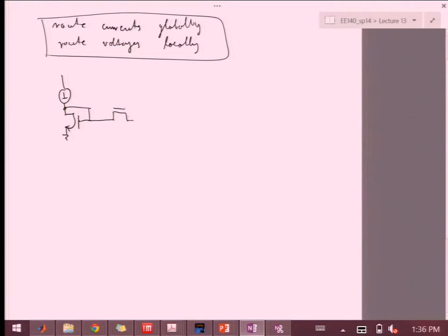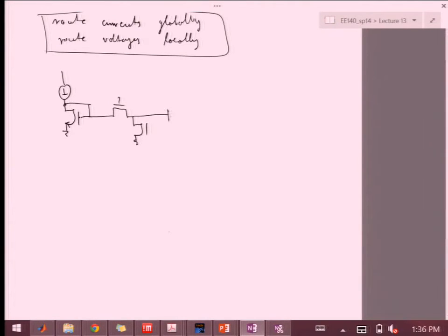So one scenario, one thing you can do is do it like this. Now, this can go on, right, to a whole string of these devices, and then you'll have a power down signal here and its inverse over here. Right? So you will both decouple the diode from the rest and then pull this node to ground. So all these are not leaking, they're all firmly shut off.